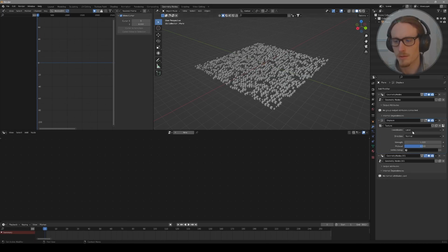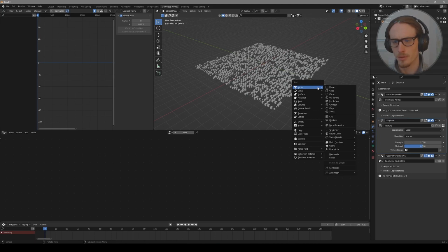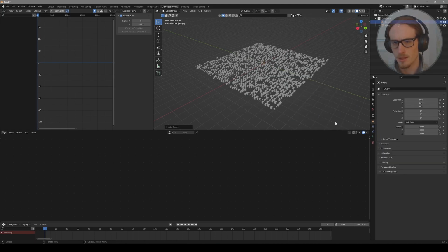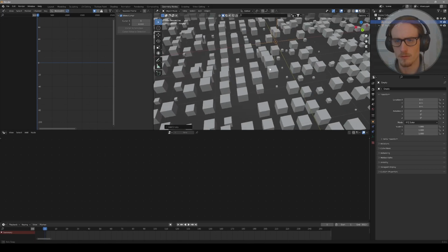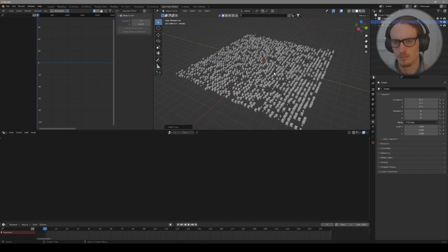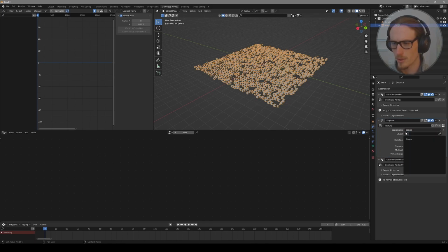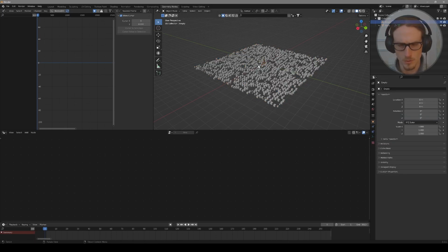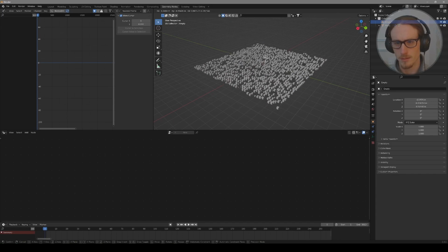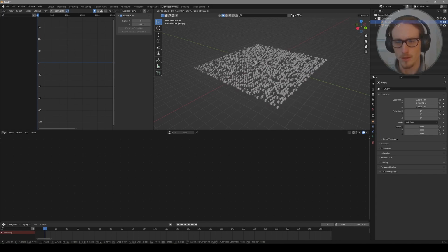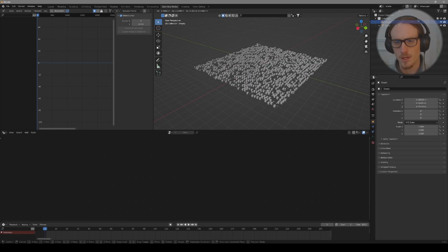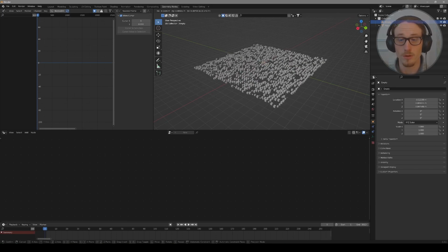And I want my displace modifier to be affected by an invisible object. So I'm up in my 3D viewport, I'm going to Shift A to add an empty plane axis. So this just adds an invisible axis right in the center. I go back to my modifiers, change my coordinates to object, and then I want to map that texture to that empty. Now if I select my empty and move it, it manipulates that displacement, changes the mapping of that displacement as well.